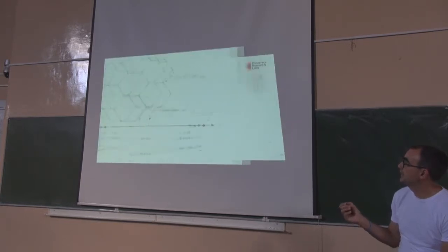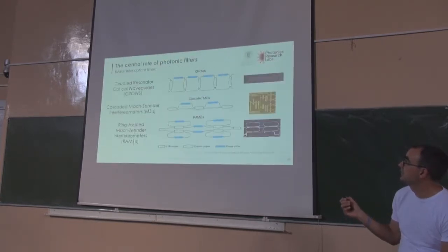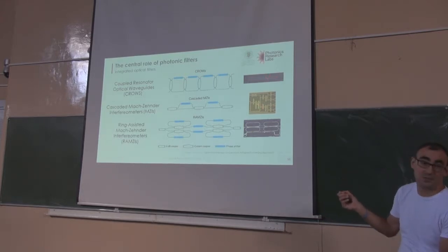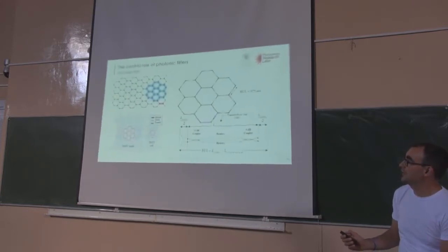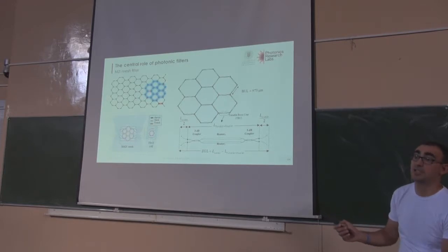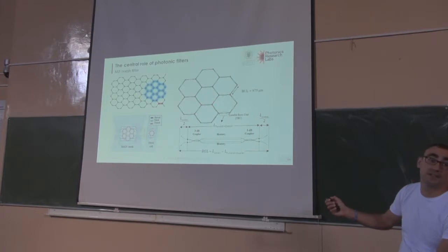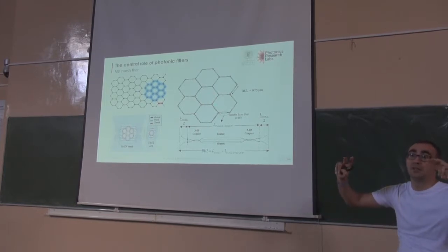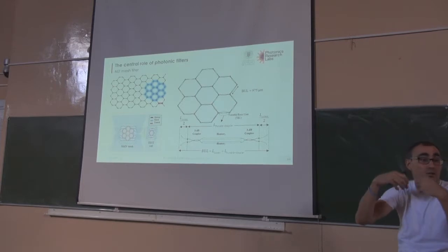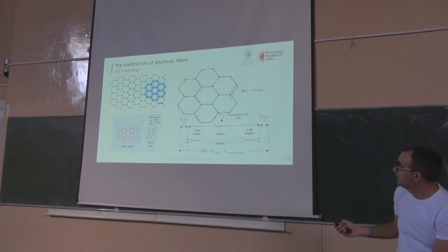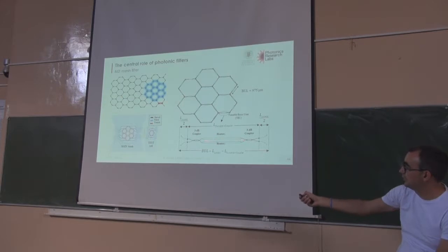I was saying these are fixed architectures. Basically, when you draw them physically, they cannot be changed. And we are researching a new architecture, which is this hexagonal mesh. Each of these lines is a Mach-Zehnder interferometer, a 2x2 Mach-Zehnder. You can set it in bar state, in cross state, or even in, I don't know, 10%, 90%. So it's a tunable Mach-Zehnder, since it has some heaters on top of the arms.